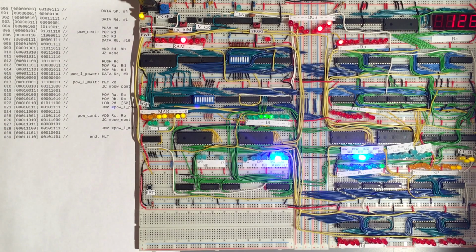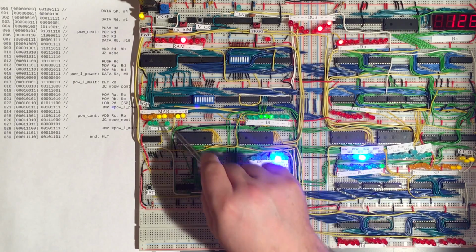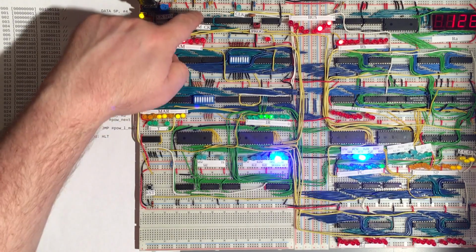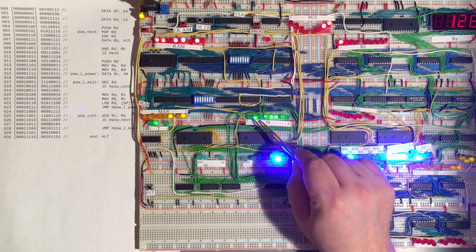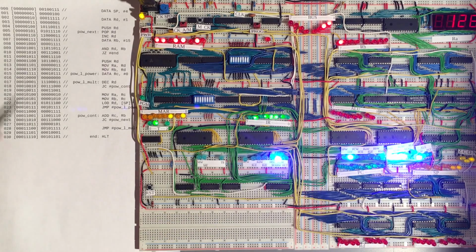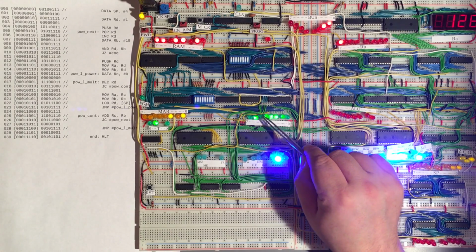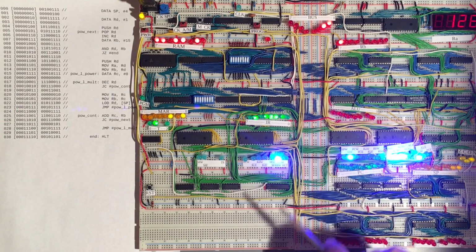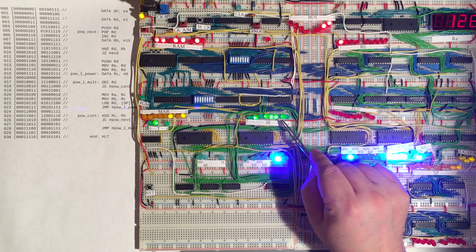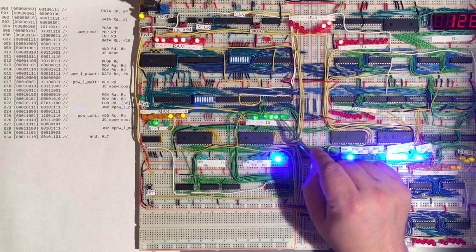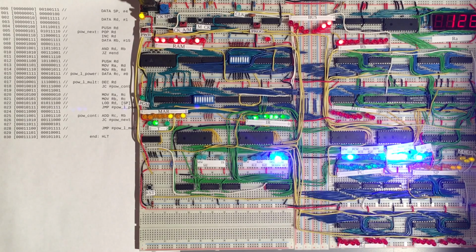As always, the first 2 micro times, T0 and T1, are always the same. So we get this 5 out into the memory address register and then read the instruction into the instruction register. So here it is, and that is our pop instruction. It is indeed a load class instruction, of course exactly this opcode here. We're loading, in this case, into the D register 011, which is a physical register, and we're loading from the source 110, which, as you remember, is the special code we invented to indicate the stack pointer with an automatic adjustment of the stack value after the operation.